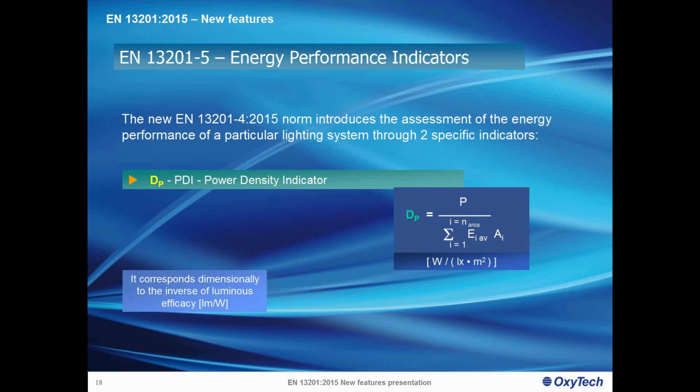So it is considering the power related to the luminaires, considering not only what is absorbed by the luminaires from the point of view of the lighting optical part, but also from the point of view of the drivers, the ballast, etc., the regulators included at the single luminaire, plus an additional power, which is the power related to the regulators that you can install at the beginning of the line, at the supply source.